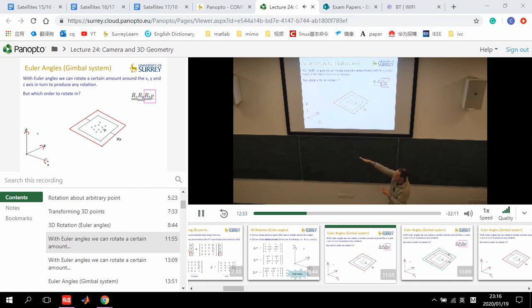So that axis that those points are pivoting on can be thought of as being a rotation around, let's call it the x-axis in this system. So we could say, I've got some matrix Rx, which we defined on the previous slide, and that is having the effect of rotating those points P some amount theta about that axis, about that pivot. Does that make sense? Imagine holding that red frame there and spinning that sheet of metal with a point stuck on it on that axis. That's what that transformation outlined in purple there is doing.